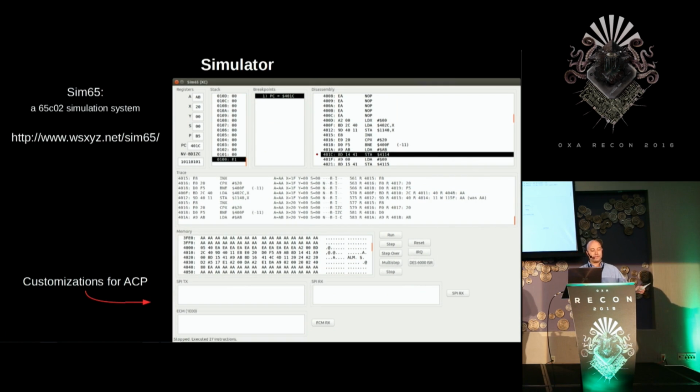In addition to disassembly, I used some 6502 simulation software to study it in a virtual CPU. The simulation is really helpful when disassembling the software. It provides a lot of insight into what's going on in the software. Since 6502 is a well-known architecture, it was not difficult to find an existing simulator, even free with source code.